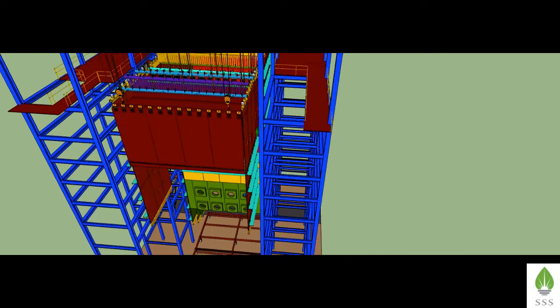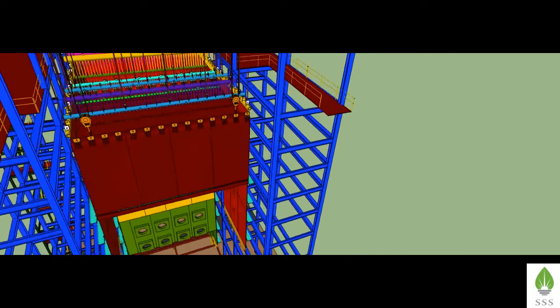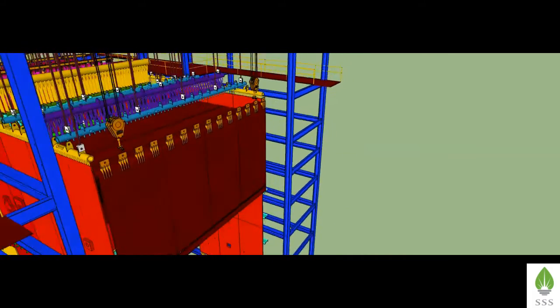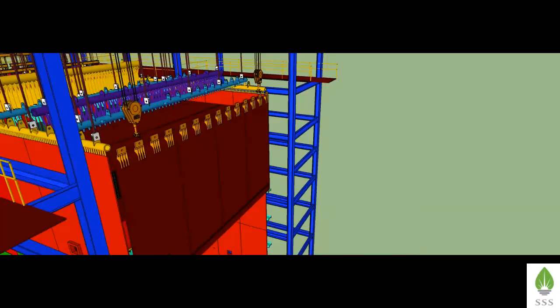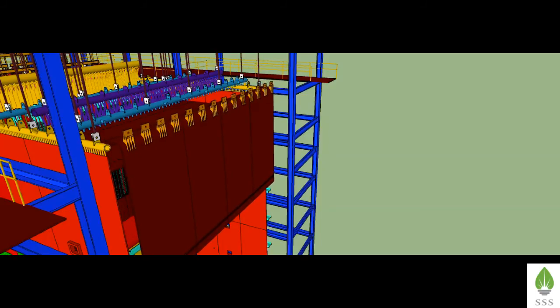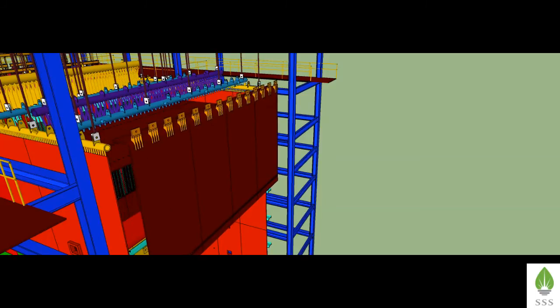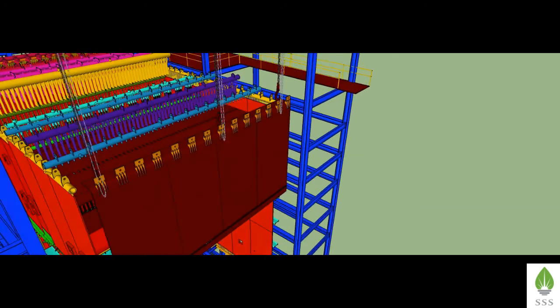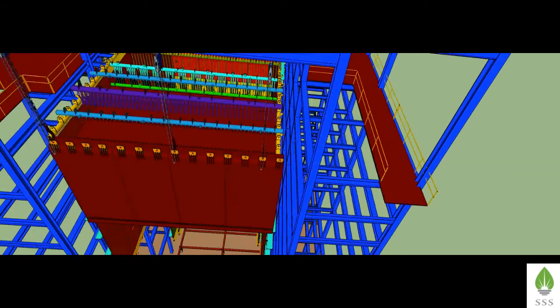The panel should not be erected to the corresponding position now. The panel has to be laced with nearby tie beam of boiler structure. This is done to facilitate primary superheater coil erection without any hindrance.